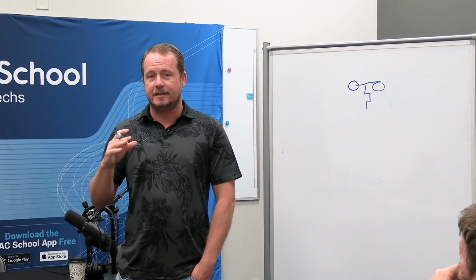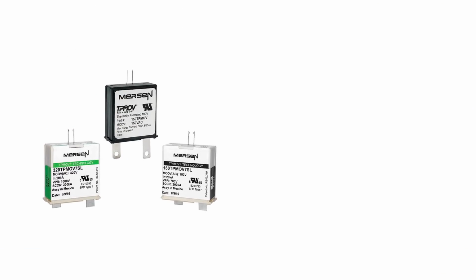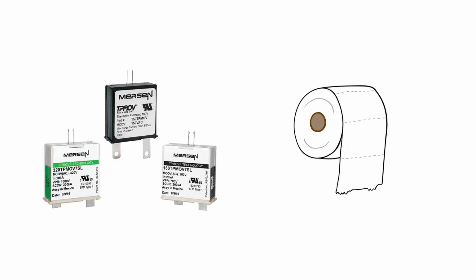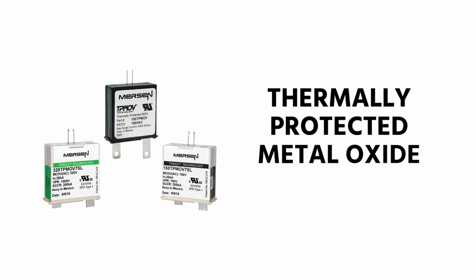An example of this is when you put a surge protector on a piece of equipment. All modern surge protectors are called TPMOV. MOV stands for metal oxide varistor. That's how a surge protector works. That's the technology. But the TP part is not toilet paper. It's not Halloween, okay? I know Bert was thinking that. No, it's thermally protected metal oxide varistor.